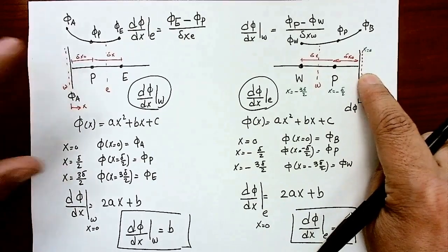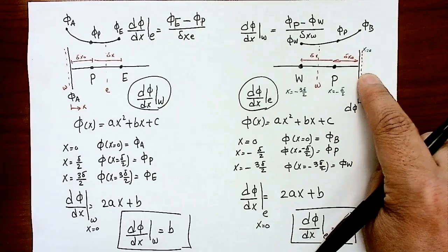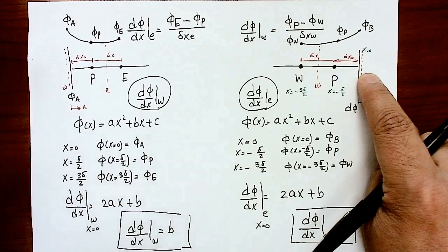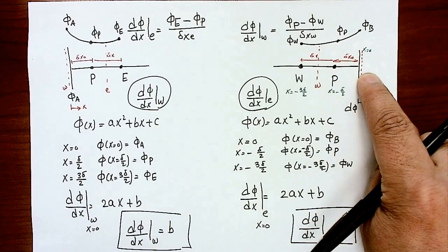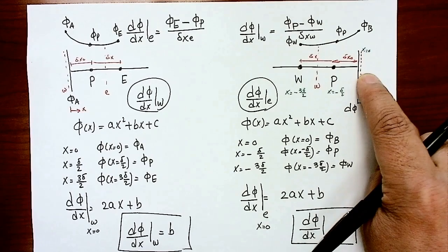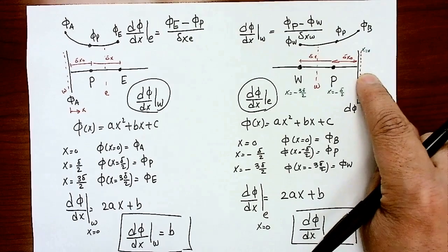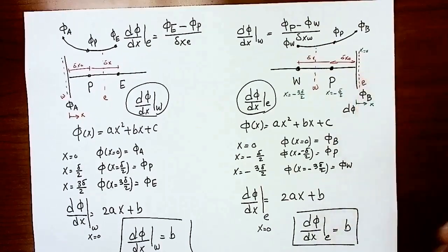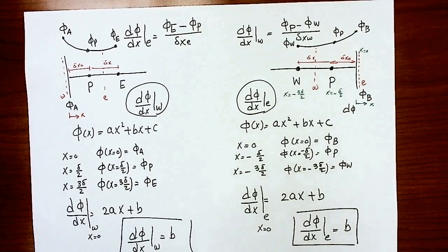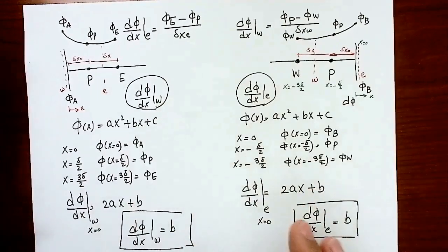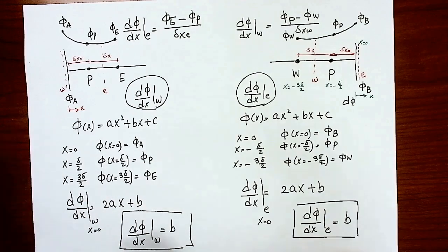This is very important. This is the exceptional step from all that we covered before. We use the central differencing scheme for convection. We use the central difference scheme for diffusion. When we went to the upwind scheme for the convection, we did not change the central difference scheme for the diffusion. It's always linear, linear, linear. But now, since we upgraded the convection term to a quadratic, it's also forcing us to upgrade the diffusion near the boundary to be quadratic as well. So this is a second major difference in the QUICK scheme.